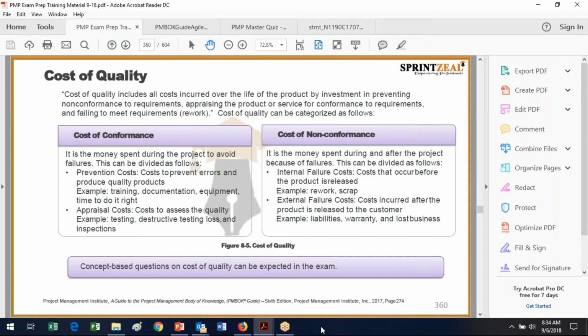In other words, obviously you have to perform testing and, say, inspections. And if you do destructive testing, say you're building fire extinguishers, anytime you use a fire extinguisher to see that it has the appropriate amount of the fire extinguishing chemical, then that fire extinguisher is destroyed, so therefore not usable. So obviously the cost of quality is producing a little bit more than you need in the case of destructive testing. And I don't know, in your facility, do you do destructive testing, or does the manufacturer? Yes, they do. So that's a little bit of overage you've got to build into the plan.